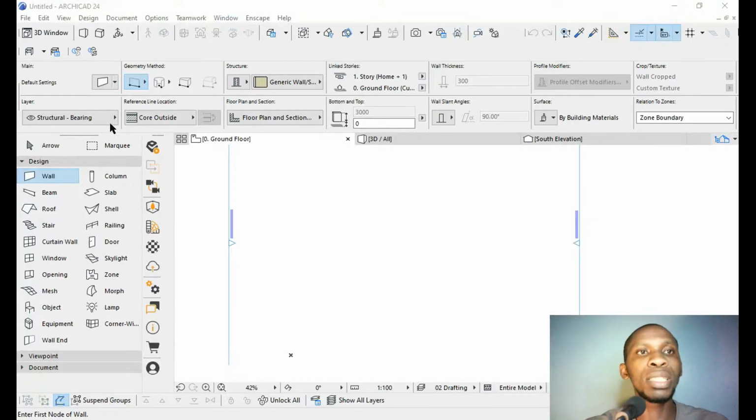Let's see the inside surface. Let's click on it and highlight it. It gives us the ability to edit it. If I click on this particular stucco, stucco white rough, it shows me different colors of paints, and there are different types of material textures, like brick texture, carpet, floors, and all these other aspects that I can use to choose the wall type. What I usually do most times is put it off for the meantime. Are we together?